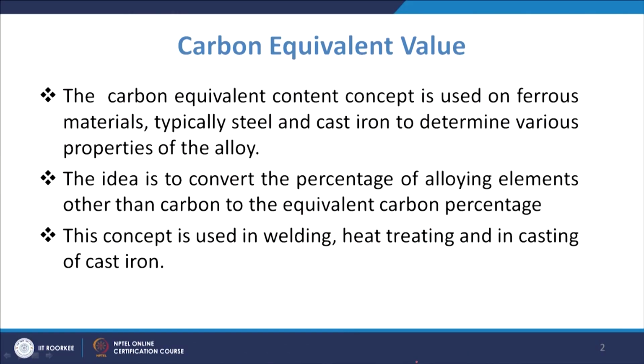So, this carbon equivalent value concept is useful in those cases. The idea is to convert the percentage of alloying elements other than carbon to the equivalent carbon percentage. Many alloying elements supplement their roles in the same direction as carbon does.